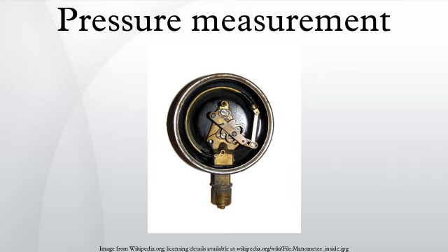Differential pressure gauges have two inlet ports, each connected to one of the volumes whose pressure is to be monitored. In effect, such a gauge performs the mathematical operation of subtraction through mechanical means, obviating the need for an operator or control system to watch two separate gauges and determine the difference in readings. Moderate vacuum pressure readings can be ambiguous without the proper context, as they may represent absolute pressure or gauge pressure without a negative sign. Thus a vacuum of 26 inHg gauge is equivalent to an absolute pressure of 4 inHg, as 30 inHg minus 26 inHg equals 4 inHg.